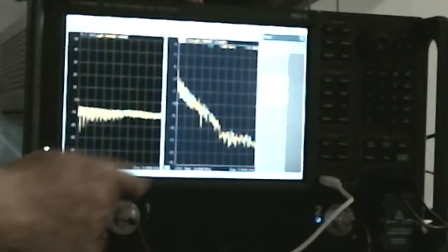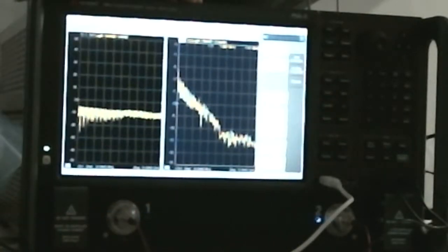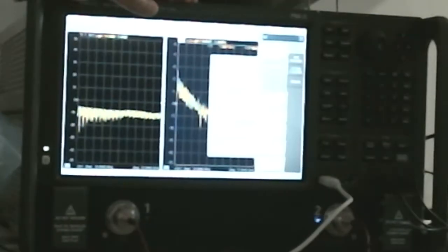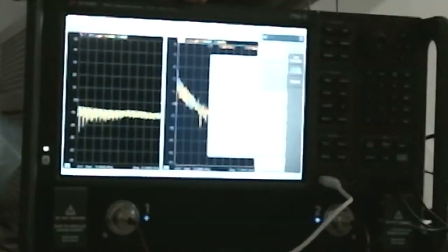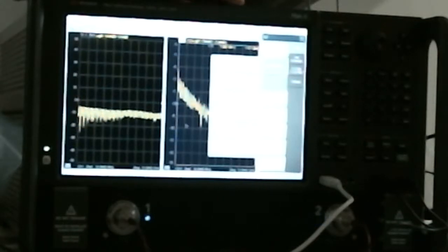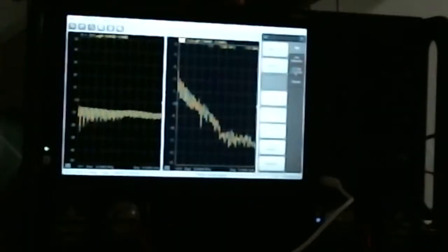Calibration substrates, right? So under cal, is there a specific one for power calibration? There is. Under other cals, you can see there's source power cal, and this will calibrate the source power of the network analyzer, which will in turn be used as a reference to calibrate the receiver powers, right? Because if we know what the source is, we can figure out what the receiver powers are. But you also see here cal sets and cal kits.